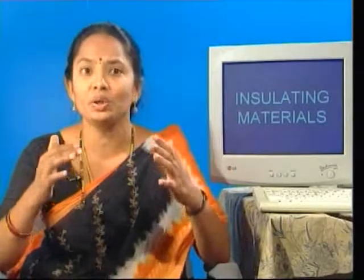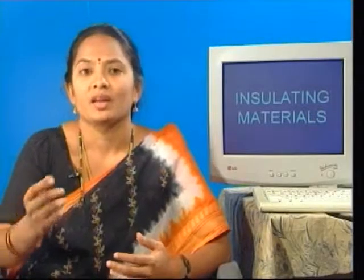The next factor to be considered is moisture absorption. The insulating material should not absorb moisture, as moisture lowers the electrical resistance and dielectric strength. Due to this, certain chemical and mechanical effects like swelling, warping, which is something becoming bent or twisted from the original shape, or corrosion may also occur. The insulating materials should not absorb moisture, but even if they do, it should be as low as possible without disturbing their electrical characteristics.